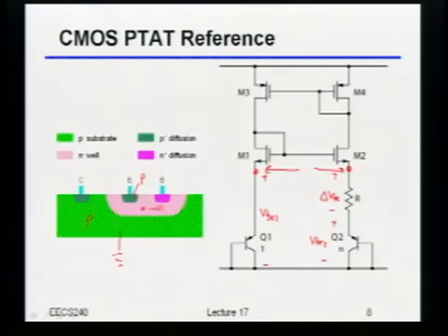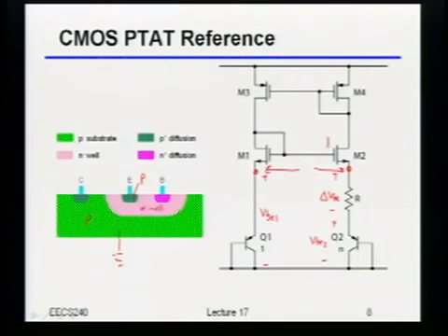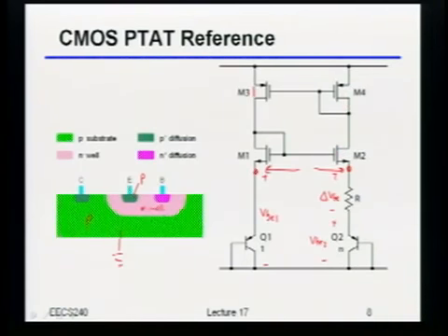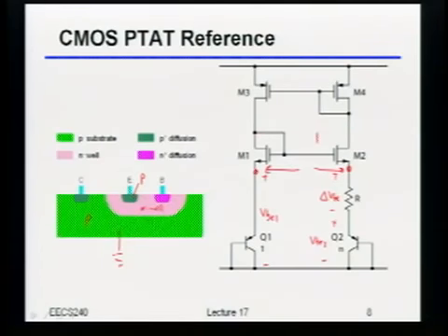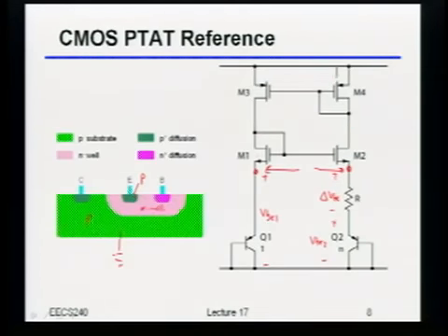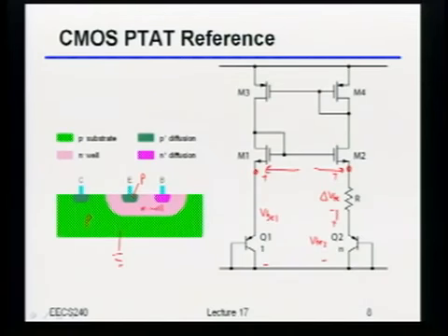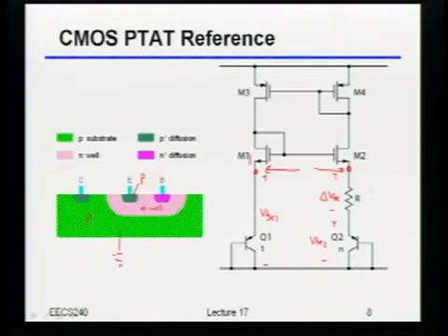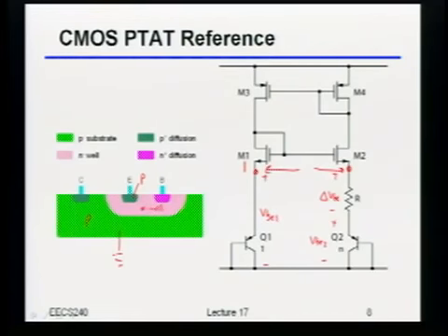The good news is that's not super complicated to do. You can do it, as an example, with the circuit I've shown here, which is very similar to that previous structure we had looked at. Essentially you have this cascode device here. You take the current from that cascode device, mirror it over to the other side, shove it back down, and then mirror it back over. So just like before, I'm forcing the current to be the same in the two branches. But by using these stacked cascodes, I'm also forcing these two voltages to be the same. Does this make sense to everybody?